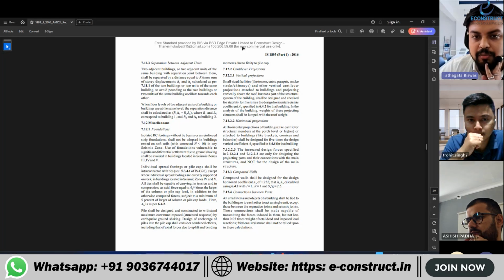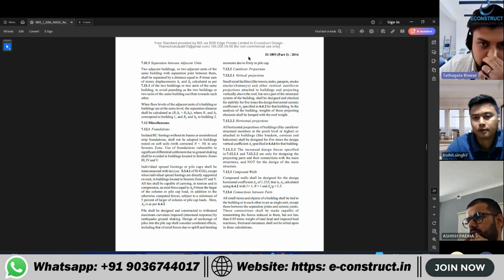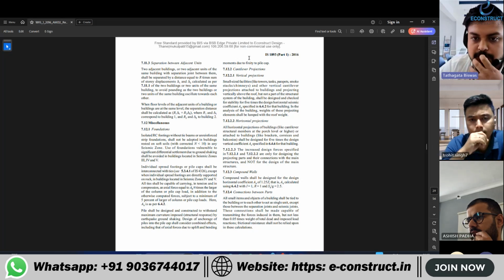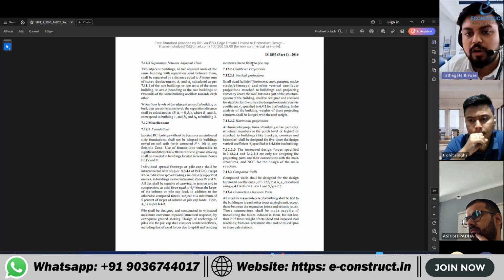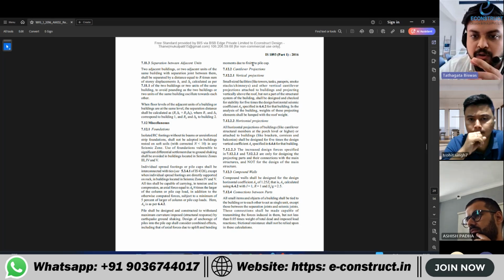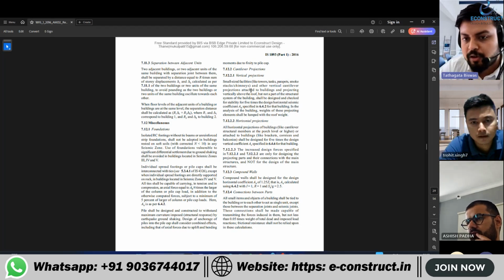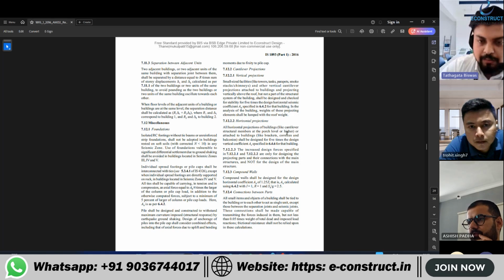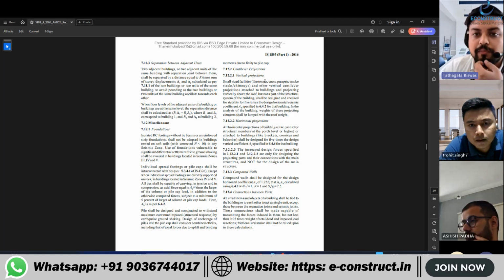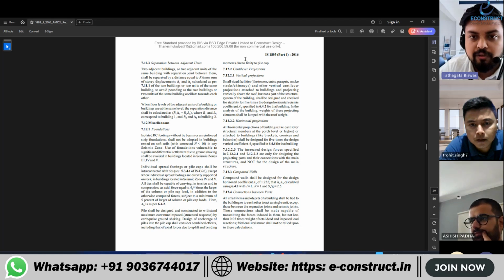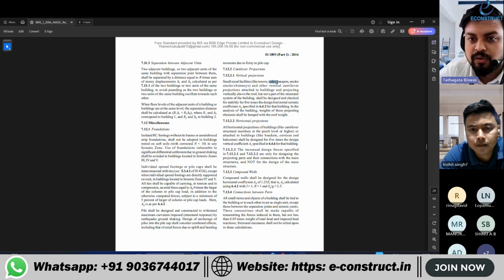Why is it asking? Because during the time of earthquake, the extra projection that is going beyond the roof is basically giving a certain lumped mass which can take the roof also along with it. So it is basically asking to check with 5 times the AH value and take that particular weight in the roof weight only, so that sort of situation does not come in our way. If some chimneys or smokestacks are there, so these tanks are not actually the tanks that we are doing.